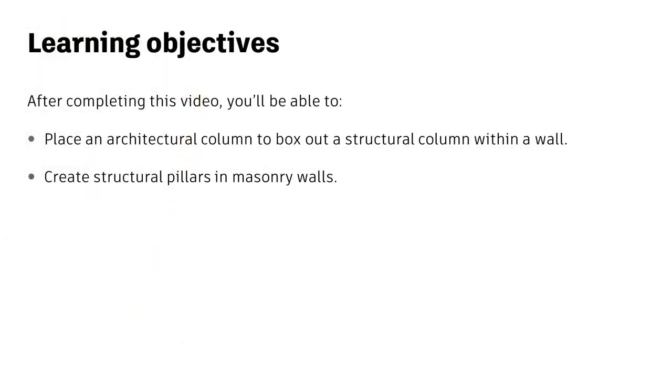In this video, we will see how to place an architectural column to encase a structural column within a partition wall, and to extend the finishes of a complex wall type around a structural column. We will also see how to use an architectural column to create pillars in a masonry wall.